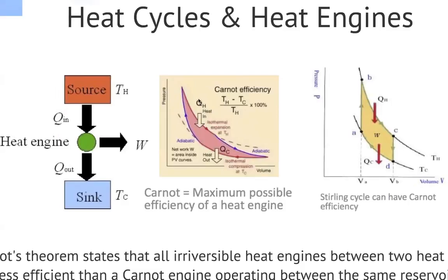This is a situation where the heat is coming into the system. We are inside the chamber, and the volume is increasing, right? It's going in that direction. The pressure is decreasing because the gas is expanding as it gets hotter. And here in the Carnot cycle, which is an ideal situation, this red part of the curve is referred to as an isothermal expansion, which means that the temperature does not change. The temperature is fixed at the hot temperature, TH, but the gas is simply expanding.